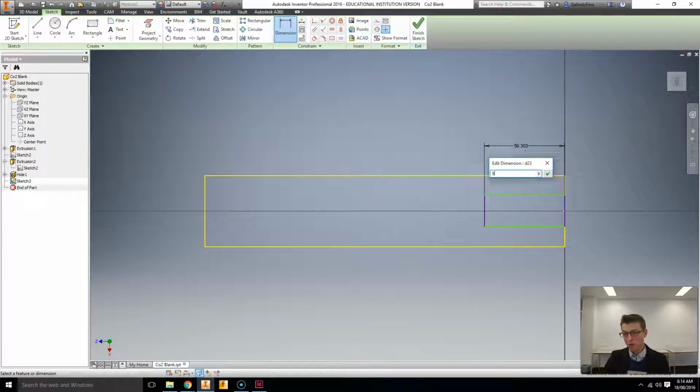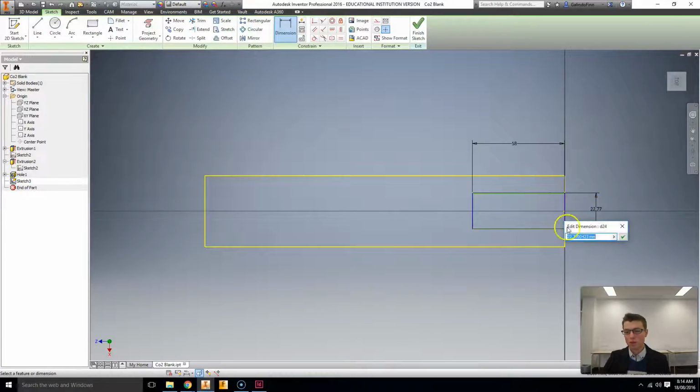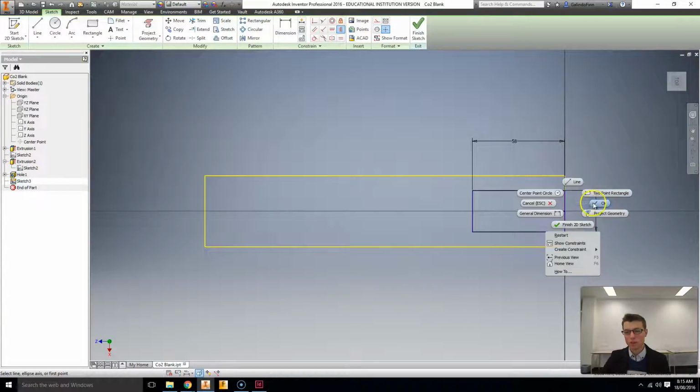Now we make the holes 55, but we add onto that 3mm at the front and then 3mm either side, so it's 20 plus 6 because there's two 3mm. Now I'm going to use the horizontal tool here to coincidence the center of the purple line to the point in the middle. Oops, that's the one. This one. Yeah, that constraint, and that will snap that in place.